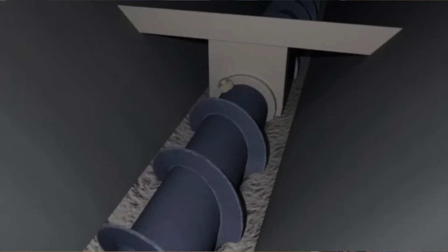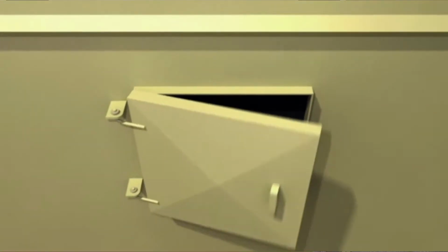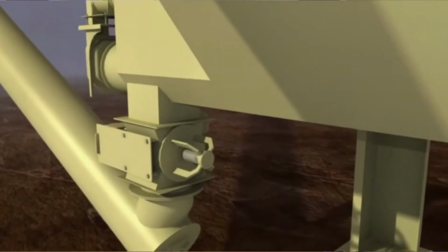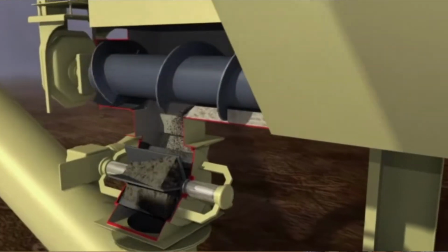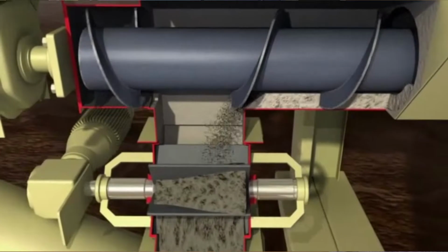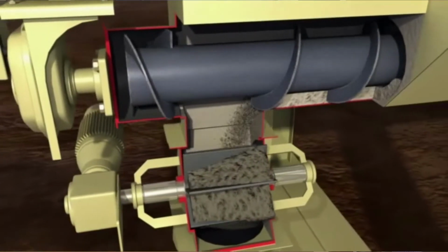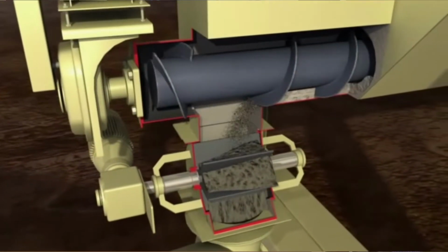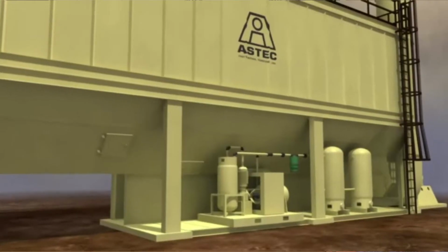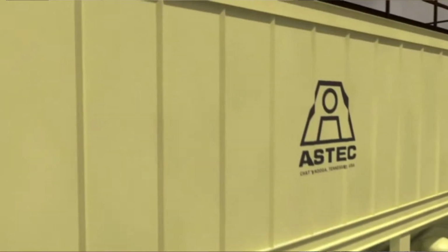As it falls down into the hopper, you can see you've got the hopper screws conveying that material back towards the drum. And there can be lots of different screws on the outside of that drum. It can be waist screws, lots of different screw configurations. Here's a breakaway of an airlock. You can see that here's the minus 100s and 200s put into the airlock. The reason the airlock is in place is basically because you want to keep the air away from it. You don't want to pull that dust back out of the screw. You want to convey it to the drum. Also, it allows you to keep surging at a minimum.